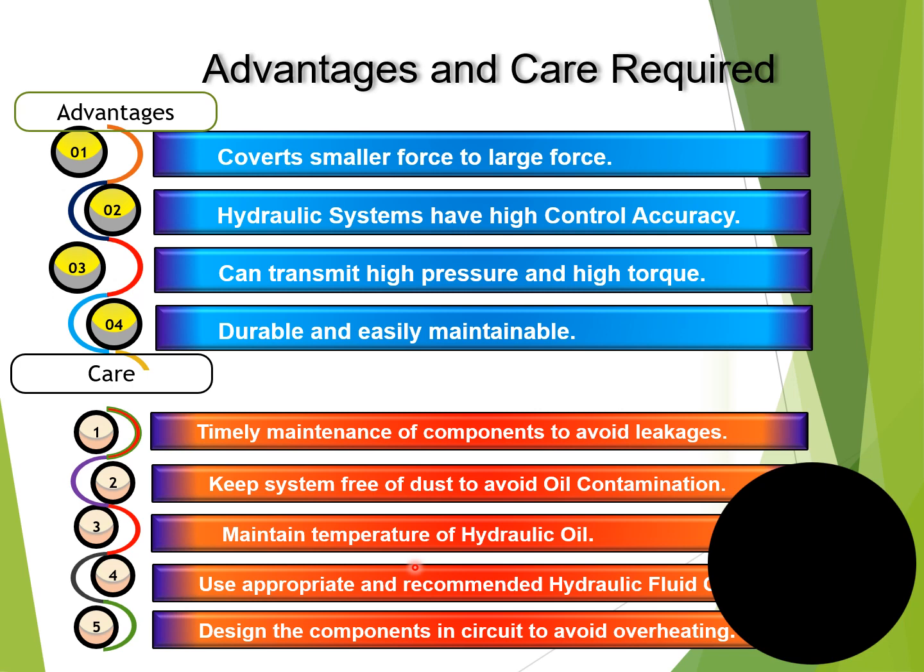Then maintain the temperature of the hydraulic oil. See, if the hydraulic oil temperature is more, then it will become less viscous, and again it is dangerous to the components in the circuit. Normally we have a radiator in the hydraulic power pack which helps in controlling the temperature. Then use appropriate and recommended hydraulic fluid only.